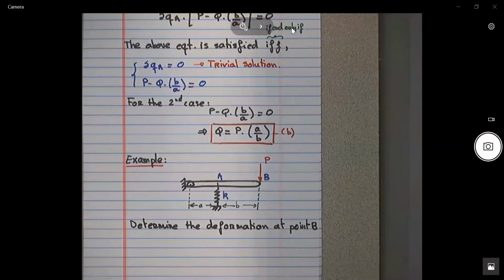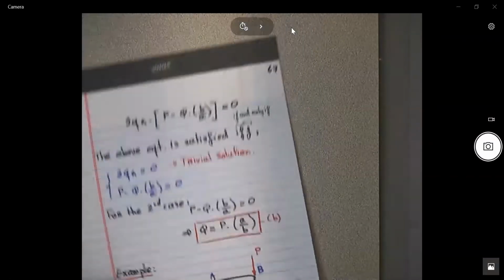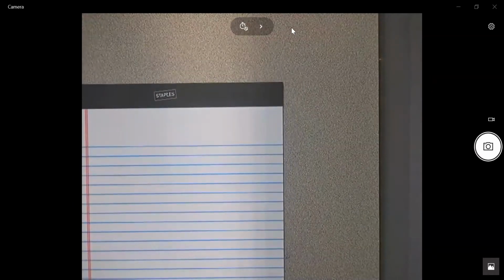If you remember, you find the moment, and then you have an equation which is the second derivative of the deformation with respect to the span-wise coordinate is equal to the moment over EI. You need to integrate twice and then solve for the two constants. You might not remember, but that's the way it is, no? Okay? All right, so let's see what it would be over here. Like always, this is the same thing in every single class. What is the first thing you need to do? You need to do a figure or some type of sketch, no?